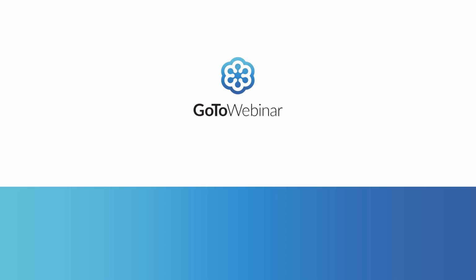asking about RCP files. So right now in Forge, we don't support point clouds, either through the model derivative service or through the viewer. We're working on point cloud support in the viewer, but that's a really hard problem to crack, displaying a point cloud in the viewer. And my understanding as well is a little bit of confusion, because an RCP file can be something from Recap Photo, which contains mesh geometry, or something from the Recap desktop application, which contains point cloud functionality. So an RCP that comes from Recap Photo, we can translate, but an RCP that contains point cloud data, we cannot translate. And the viewer does not handle point cloud right now.